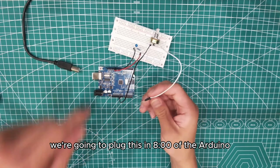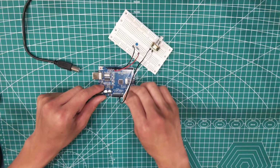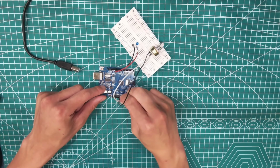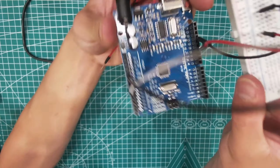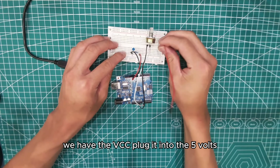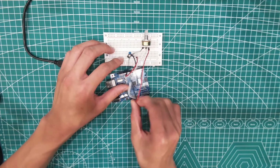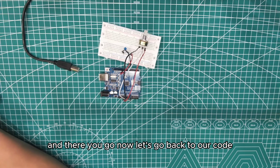We're going to plug this in A0 of the Arduino. So A0 is at the left bottom corner. As you can see, A0. And finally, on the most right-hand side, we have the VCC. Plug it into the 5 volts. And there you go. Now let's go back to our code.